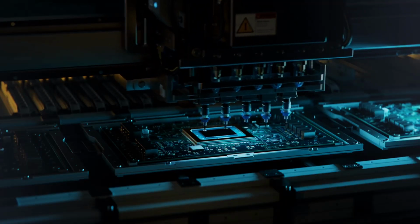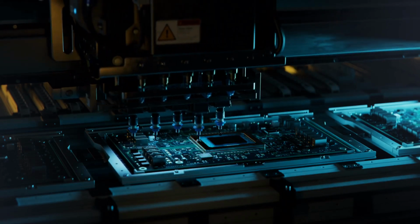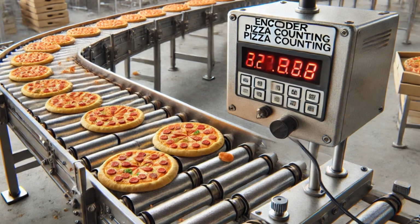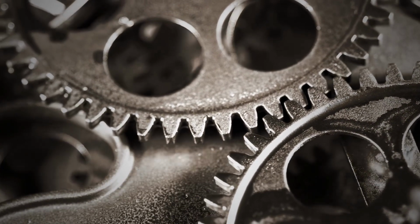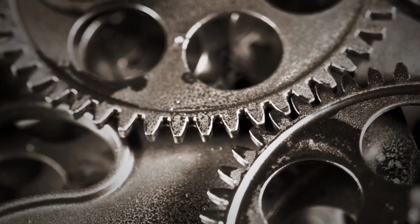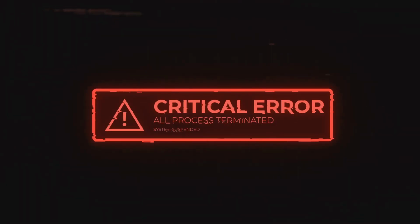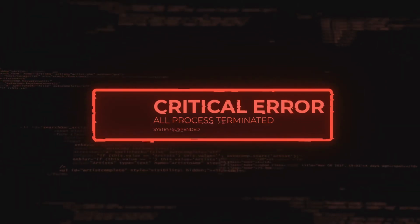However, various factors such as signal interference, mechanical faults, or software glitches can disrupt this process, leading to miscounts or double counts. Signal interference, for instance, could arise from nearby electronic devices or power lines, affecting the accuracy of your encoder's readings. Mechanical faults might include wear and tear on the encoder or misalignment of its components, leading to incorrect position detection. Software glitches could result from bugs in the counting algorithm or improper integration with other systems.